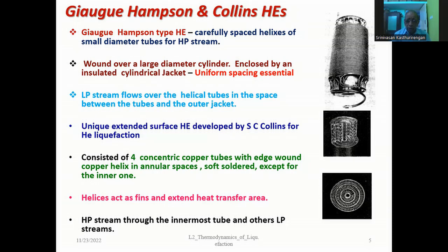Now, this sort of heat exchanger will have end connections wherein multiple tubes will be joined together. So in other words, you will have bundles of tubes which will be joined together at the ends, and they will form a total high pressure output. Similarly, the inlet also will have similar bundling of the tubes, and a zone where the input stream is distributed to the smaller diameter tubes.